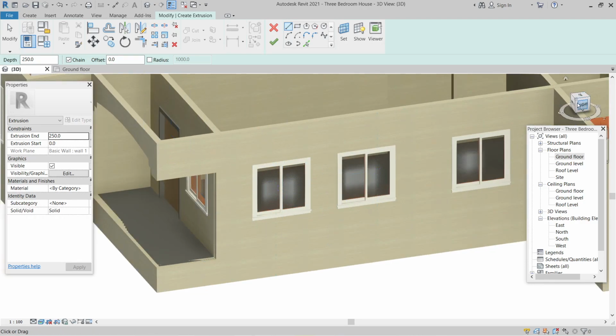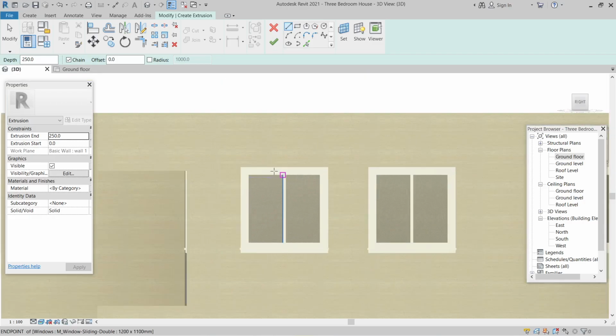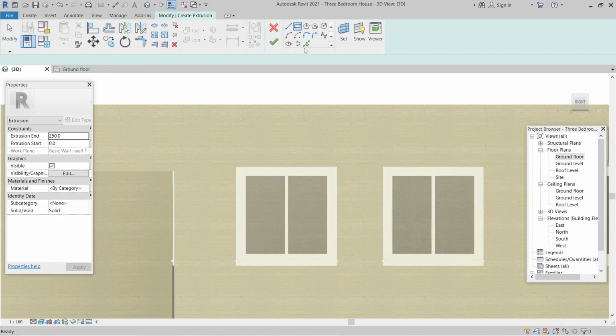So you position it to the right, then you zoom in, and then you pick our rectangle, start from here to here, very good. Then we offset maybe 50 and offset 10.